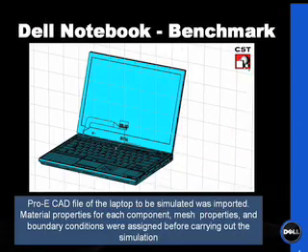So here a Dell notebook was used as a benchmark by importing it. This is a generic Dell notebook which is already available in the market. So we imported this in the simulation tool, and usually I found a STEP format better to use instead of a SAT format, because when you import a SAT format CAD file, the names are lost, whereas if you import a STEP format, all the names are retained. So this way you know which component is which part.